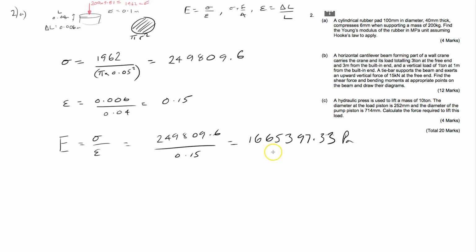Now, if I had my nice Casio calculator, I'd just press the ENG button to convert that, but as I don't, I'm going to do it manually. 1, 2, 3, 4, 5, 6, which will equal 1.67 megapascals, which is obviously 1.67 times 10 to the 6. Quick check against the answer sheet, and we find that is correct. On to question 2b, which is a little more involved.